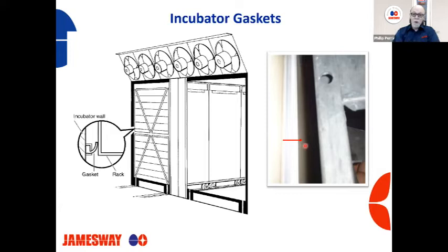So where do you think this air is going to flow? Is it going to flow through our eggs here, or is it just going to come right through here where there's no resistance? So we've got to get these gaskets worked out, and I know that requires a lot of maintenance and upkeep on these machines. About the time you get all your gaskets replaced, another one becomes torn or has another failure. So just keep up on these to make sure we get the proper flow.